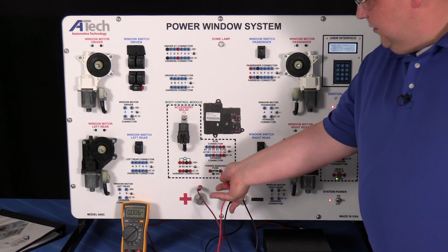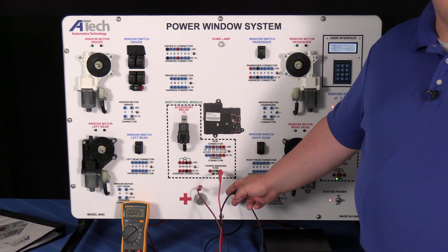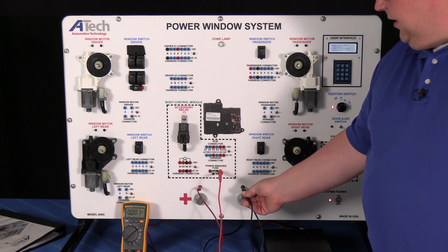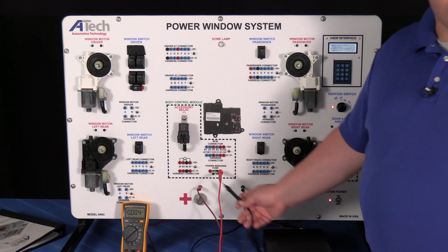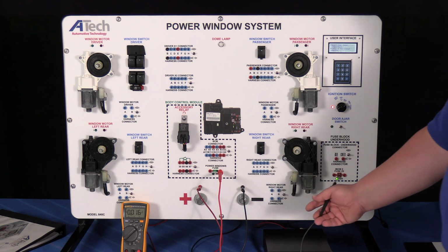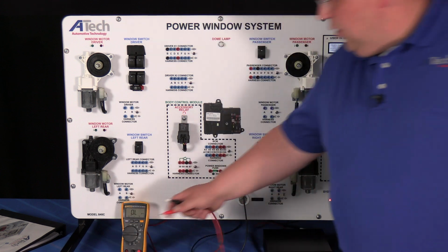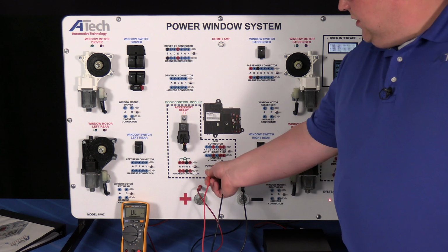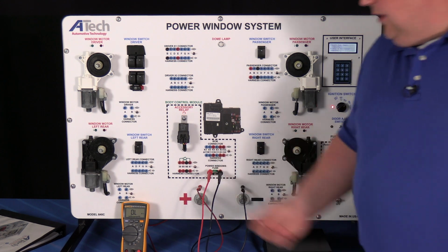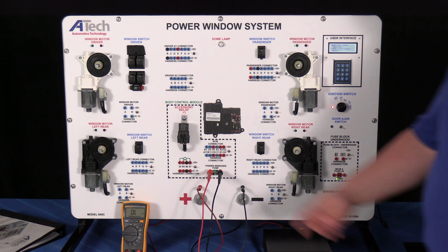That one put in there, that tip jack plugged in, and I've got 0.005 volts. So that tells me that something's going on here. That tells me that this fuse is potentially blown. So if we want to see if the fuse is actually blown, we can move our meter to check for resistance. We can go on one side of the fuse and down to the other side of the fuse. There should be continuity between those 2 points, and there is not. So the fuse is blown.